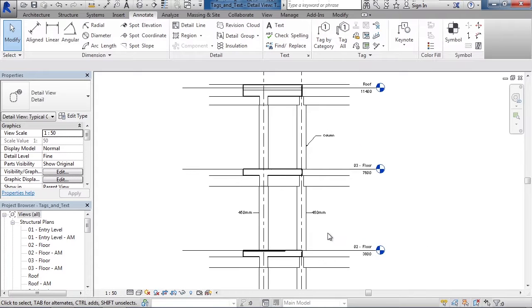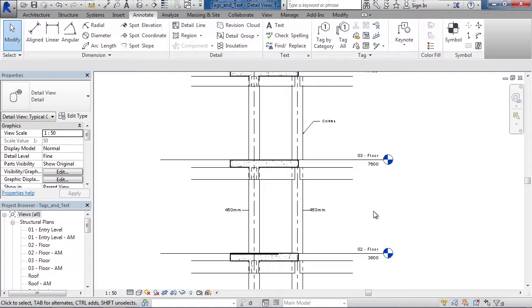The size of the text and the arrows, even though set based on the font that we used, is also controlled by the view scale. So as you change the scale, making it larger or smaller for the view, this text and the arrows will size appropriately when placed on a sheet.